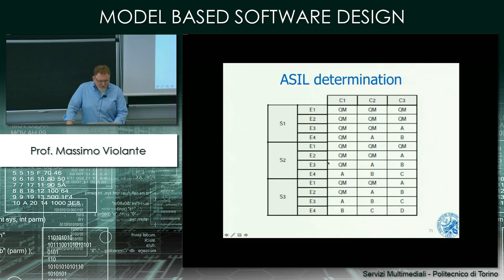If we move forward, we can see how the ASIL could increase. Severity 1, very light injuries, but this is something that happens very often, exposure 4, and when it happens, it's not controllable. Well, this is ASIL B, but it's already in the middle of the criticalities, but this is something that we have to take care of. We can't just say, oh, don't care, it's just quality measure. No, this is something that has an impact on the driver.